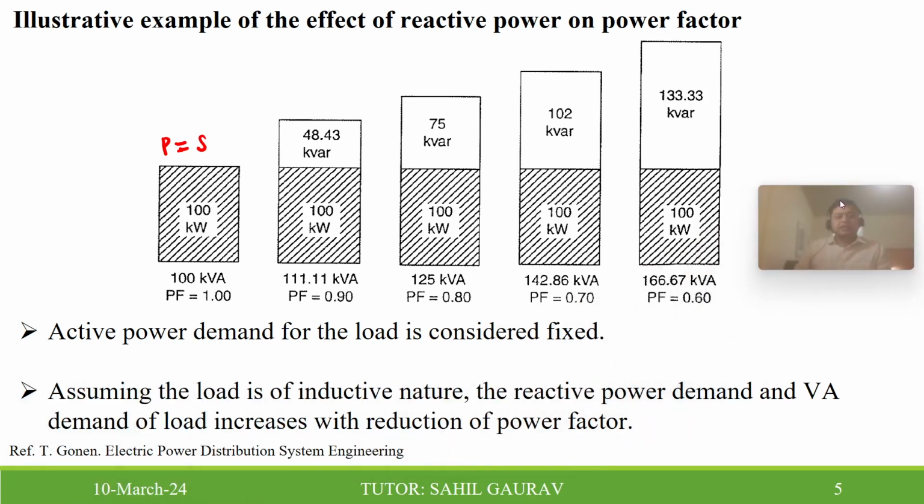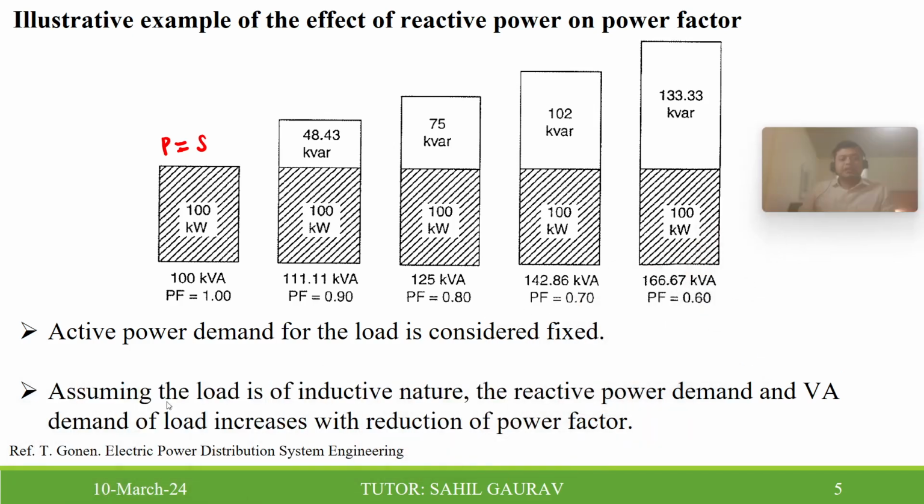And this is from the class notes: what is the effect of active power on power factor? Here we have considered that the active power demand of the load is fixed, and if you assume this load is of inductive nature, then the reactive power demand and the VA demand of the load increase with reduction of power factor.